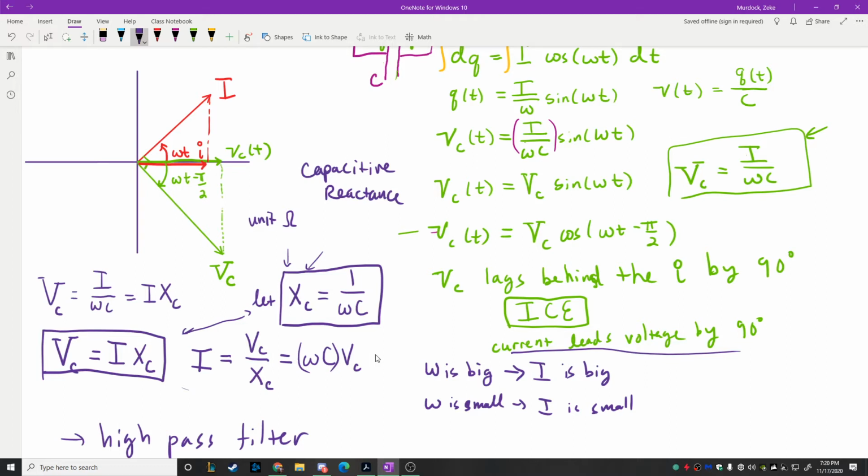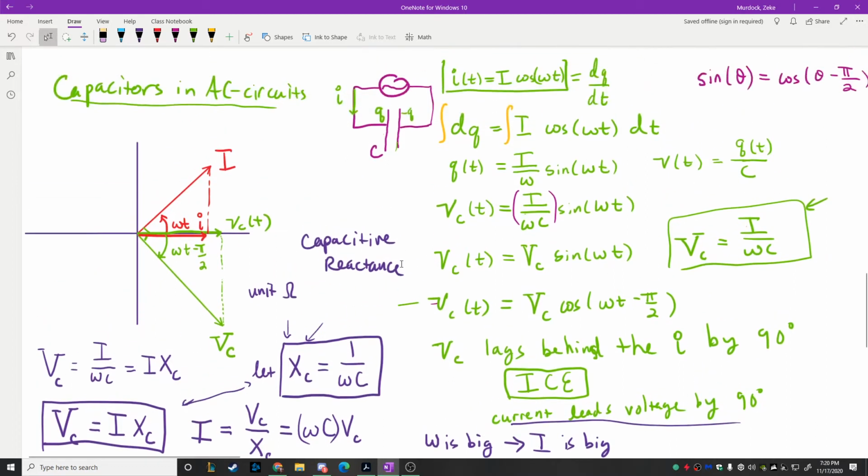So, if you think about this, this is something that's really unique about AC circuits. In a DC circuit, what a capacitor does is basically just hold charge for you, right? But in an AC circuit, it acts as a kind of rebound point for the current in the circuit. And if you let it charge up too much, then it's actually going to produce a resistance to that current, right? Because if the current's flowing in this direction and there's a bunch of charge on the plate, it's not going to have an easy time pushing more charges onto that plate. Because that's what the capacitor basically does.